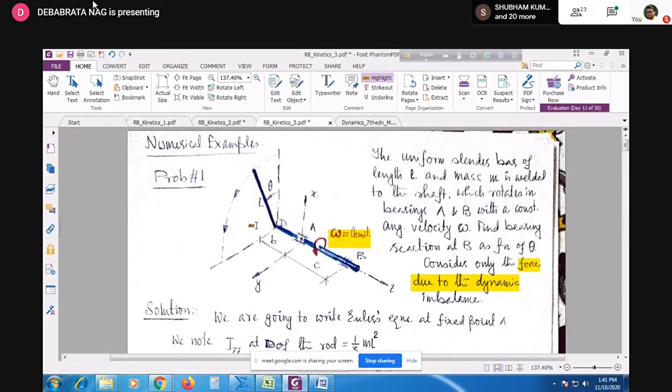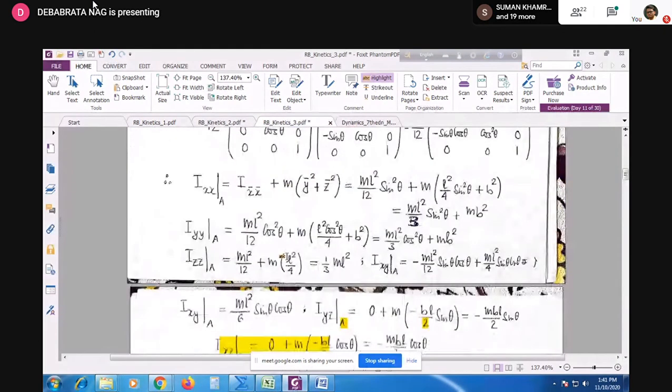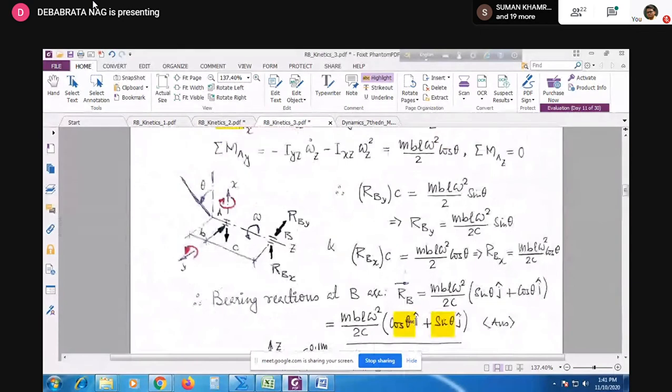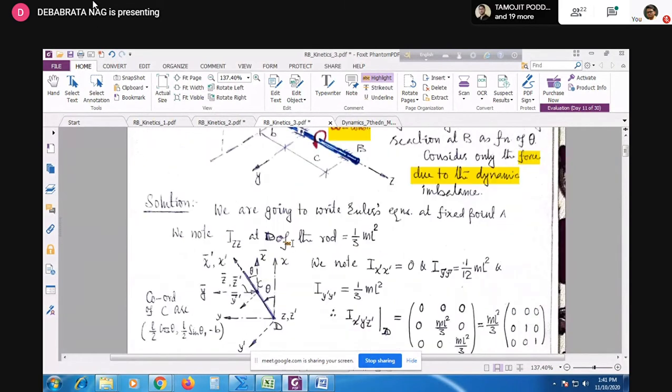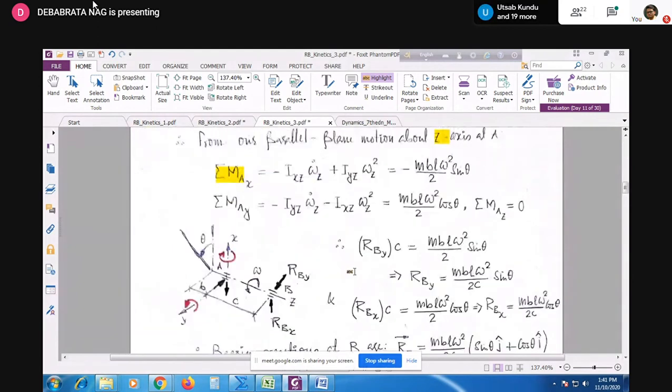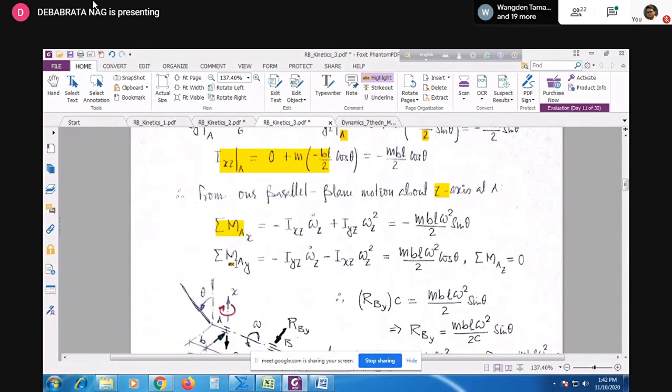If you put theta equal to 90 degrees, in that case obviously cos theta will be 0, so there will be no I component because cos theta is associated with I. Since these xyz axes are body fitted, when the rod is here, this is still x, this is y, this is z. So at theta equal to 90 degrees you do not have any I component of force. All the forces will be J components. And that will be really tight.